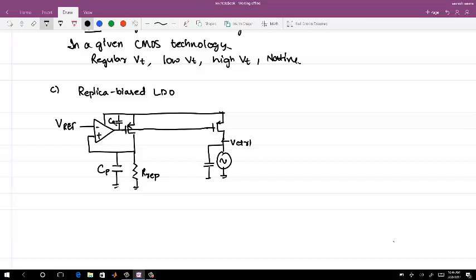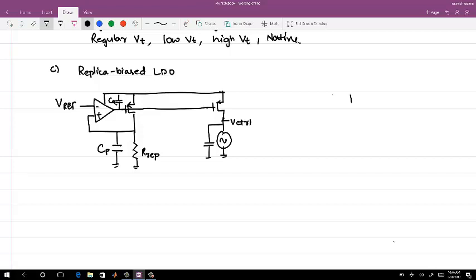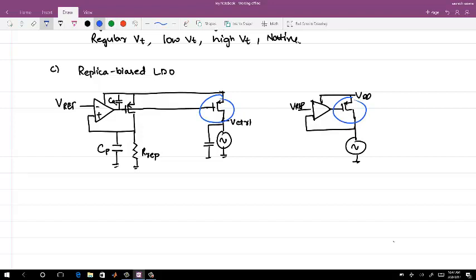Okay. So let me ask you this. In the earlier case, this was the earlier case, Vref, VDD, right? These two transistors effectively do not change if I am running the oscillator at the same frequency. So the capacitive load at CA will not change much if the replica is a much smaller version of the main current source. This is M replica and this is the main current source. The replica is normally much smaller than the main current source, so your CA will not change that much. What comes with the parasitics, the additional you put, is a different case.